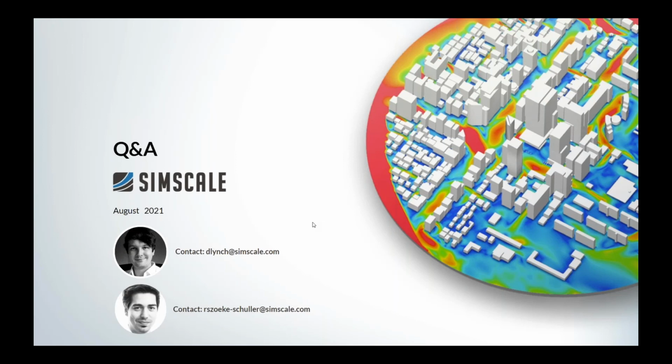This is very easy to even get from Excel once you have the original data. But yeah, tools like Energy Plus help. There's also other websites available like this Ladybug EPW map, where you can not only download EPW but also stat files that come at the same time in the zip file that you get from there.